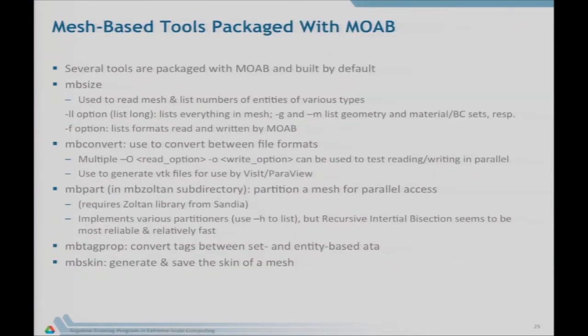There are a number of tools packaged with MOAB. Those are executables that are built with it. So typically the first thing I do when I look at a new mesh, I'll just run mbsize on it, which tells me how many entities are in the mesh, and different options control how much it tells you about what's in there.